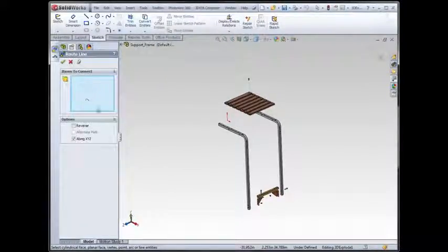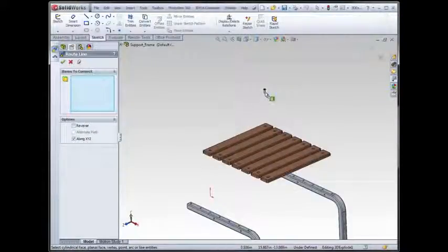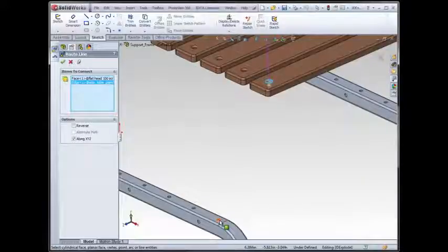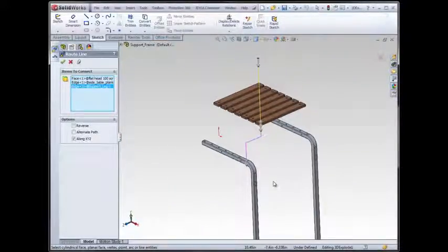We're going to choose items to connect, and in my case, because I've selected the option, it will show a line along the XYZ coordinates. So for example, this screw will move through this plank, the corresponding hole in the plank, and then also it should be connected to this support leg. Green check, and I get my route line.